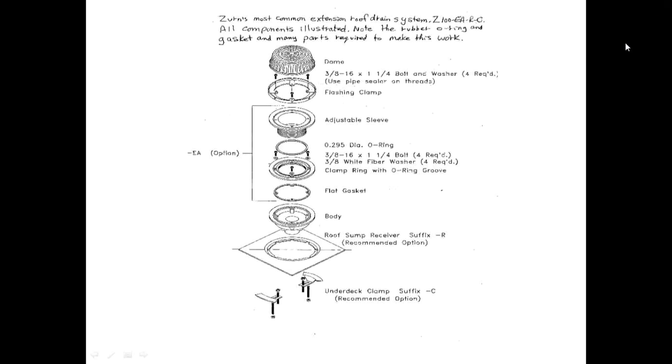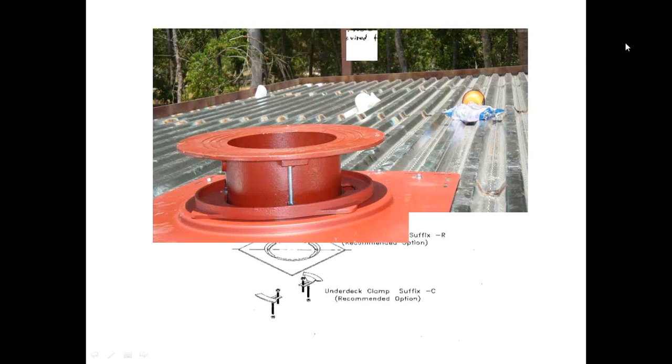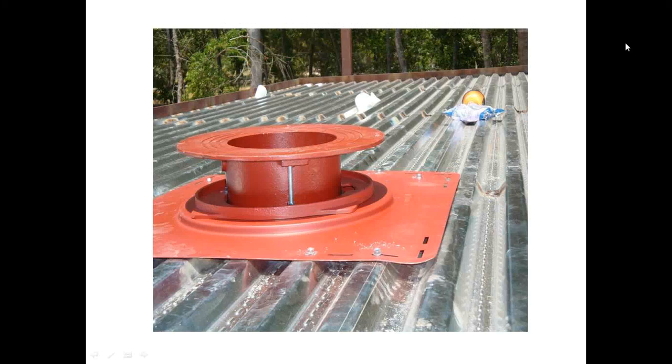between their design and our design, which we're looking at now, is with our design there are no gaskets. There's no threaded adjustment. You have infinite adjustment because you have the HS3 hardware studs. If the HS3s aren't long enough, you can easily go to Home Depot, get a longer hardware rod, and go to whatever height you want. But we found that the height that we give on the HS3 is enough for most insulation applications.